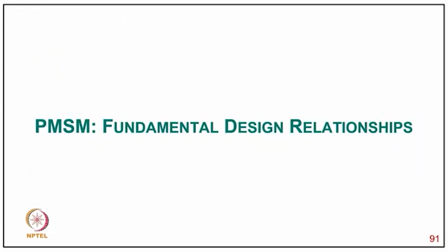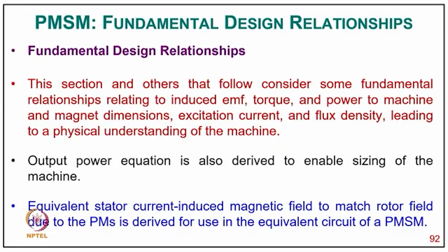Now coming to PMSM, fundamental design relationship. This section and others that follow consider some fundamental relationships relating induced EMF, torque and power to machine and magnet dimensions, excitation current and flux density, leading to the physical understanding of the machine. And the output power equation is also derived to enable sizing of the machine. An equivalent stator current induced magnetic field to match the rotor field due to the PMSM magnets is derived to use in the equivalent circuit of the PMSM.